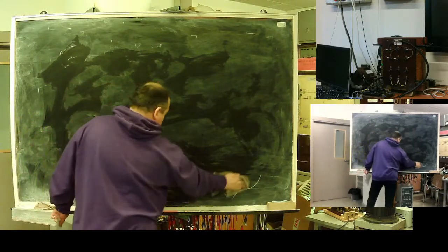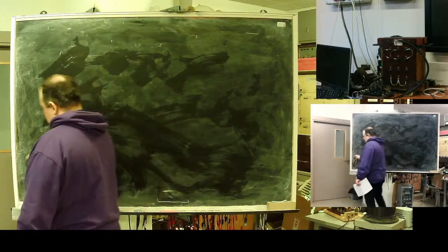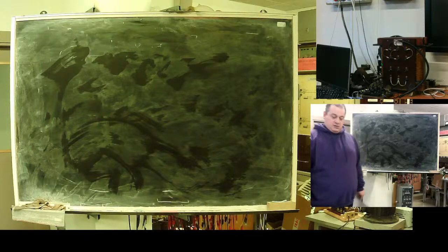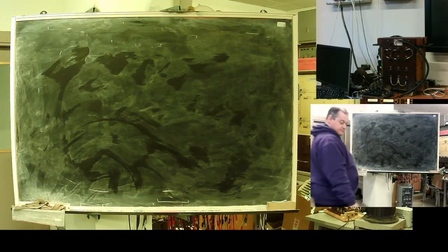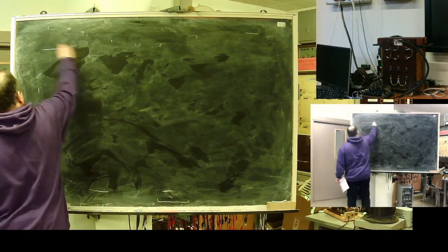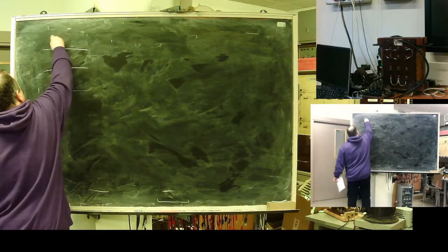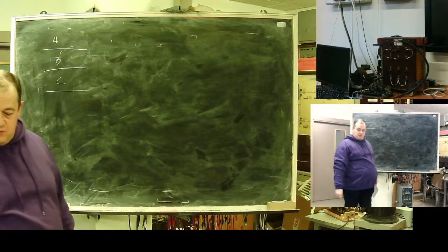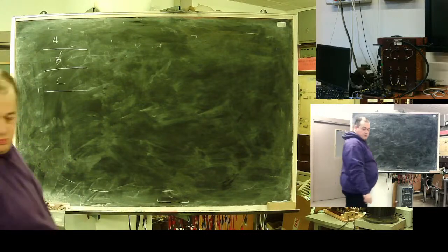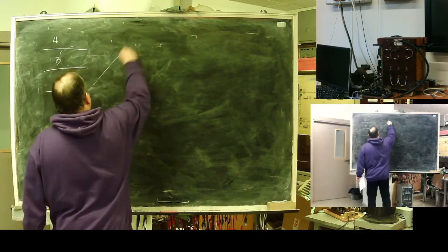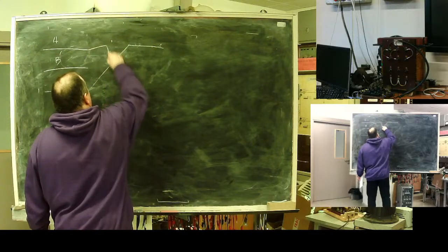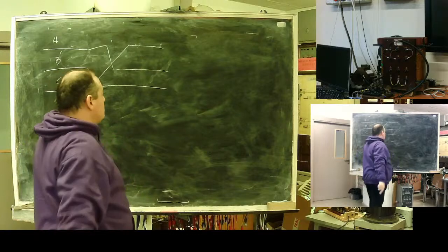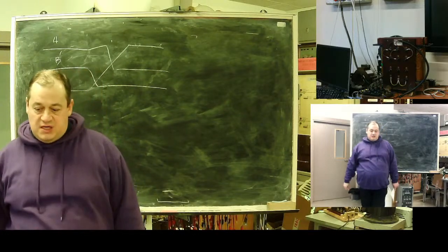To avoid line asymmetry, at first by capacitance. The trick is done: A, B, C. Next swap A, B, for example. First transposition stage.